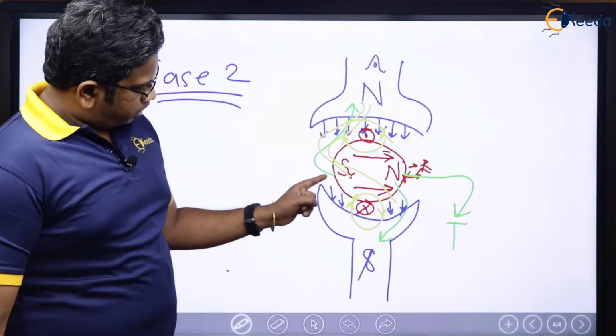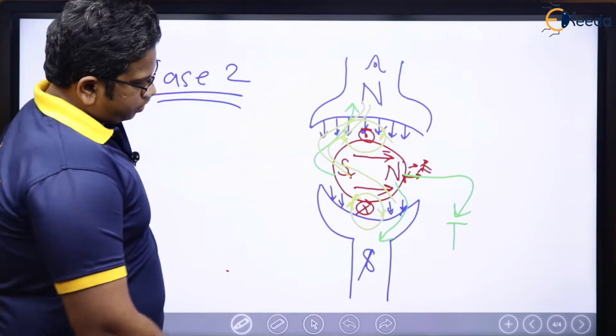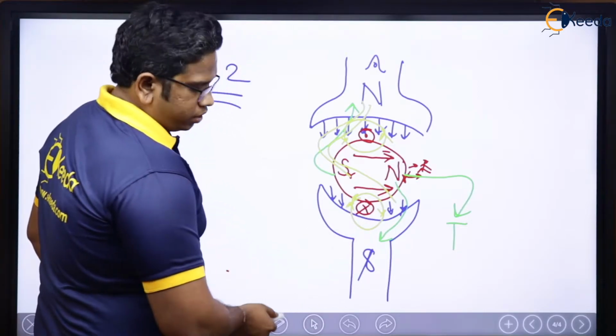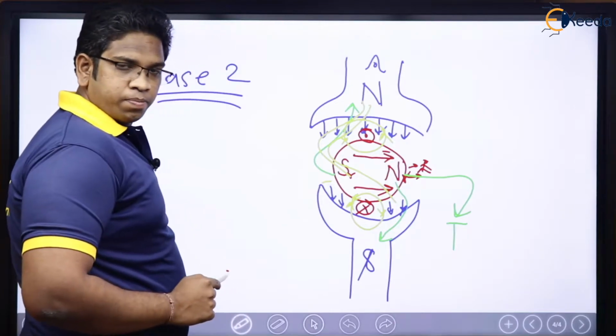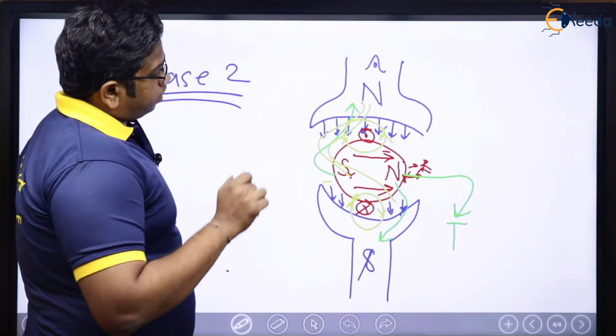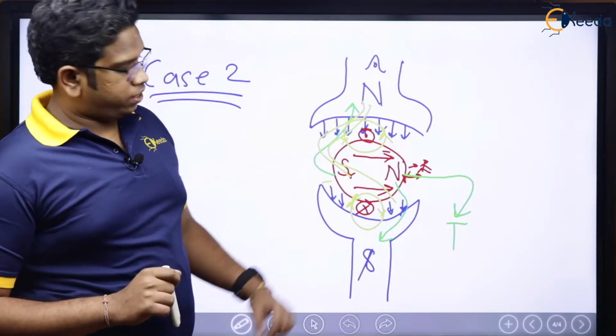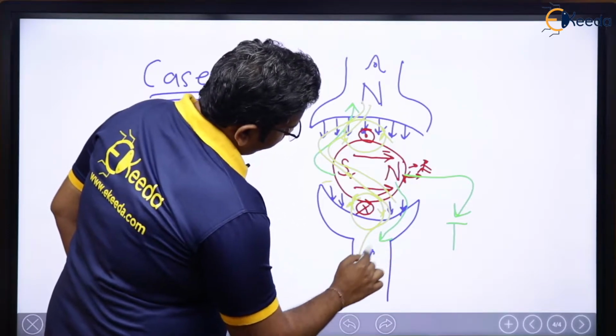Now stator flux lines are like this. See here, these are the rotor flux lines. Rotor flux lines in this particular area are opposing each other, right? And in this particular area, rotor flux lines are aiding the stator flux lines, which means it is going to come like this. Stretching will happen like this,